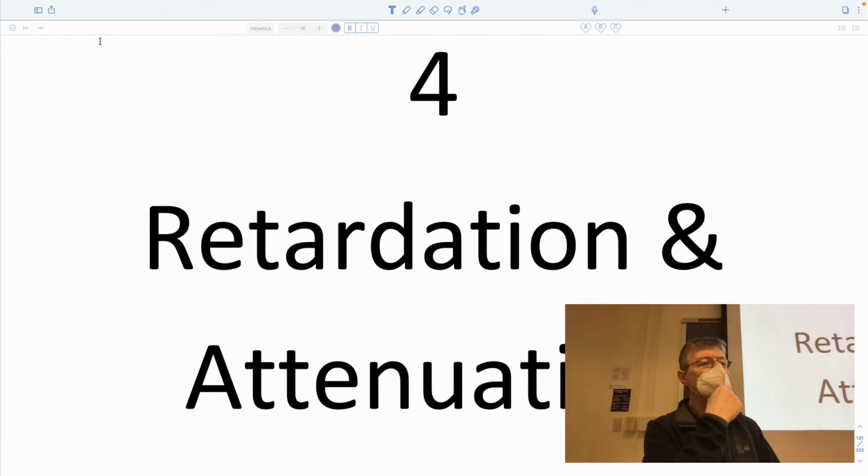The last three sessions, 3.1, 3.2, 3.3, we've been talking about how dissolved components get transported downstream, and how their concentrations vary with location and how they evolve with time. And what we haven't said, but was implicit in it, is that we've been dealing with things like chloride ion, which are conservative. And so what conservative means is that any amount of chloride ion that gets dissolved in the water stays in the water as it goes down gradient.